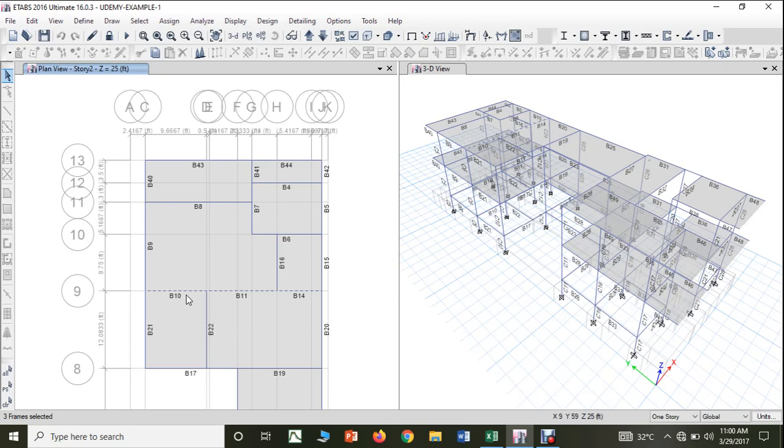Not to the entire floor I'm telling, but at least to one stretch of columns, one stretch of beams, you're supposed to provide that continuous reinforcement so that it will be easy for us to execute in the site. So by keeping that concept in mind, now let us start doing the grouping.